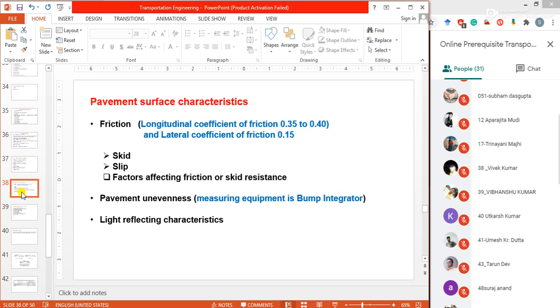The coefficient of friction, another name of which is skid resistance, offered by the pavement surface under various driving and surface conditions, is important with reference to safety. The maximum coefficient of friction comes into play only when the brake efficiency is high enough to partially arrest the rotation of the wheels on application of brakes at low speeds.